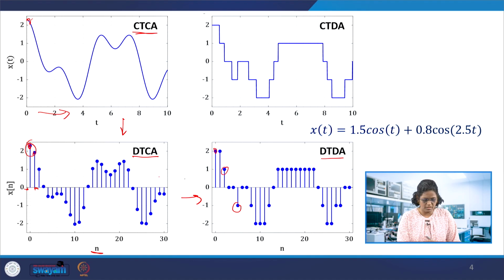So these are the three cases of signals which we had seen. This would also be part of the ADC and DAC process, whereas this one we can say is continuous in time, discrete in amplitude. So once we have this signal, and if we process it in the DSP or FPGA, the outcome, the samples which are coming out of it, would first be like these samples, and then these samples will be sampled and held for a while, till the next sample.